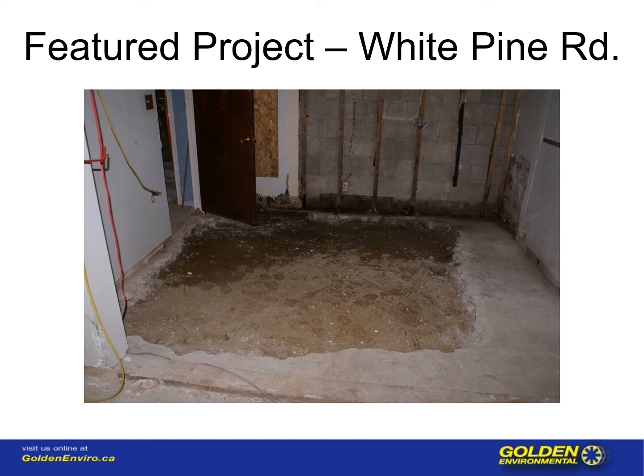Sometimes it is advantageous to break up the concrete floor in a given area. Not always, but in this case, it did prove to be advantageous in that it gave us direct access to oil-soaked soil underneath the concrete floor. If we were using a chemical oxidant, we could simply drill holes through the concrete floor and inject enough volume that it would push up against the underside of the concrete floor.